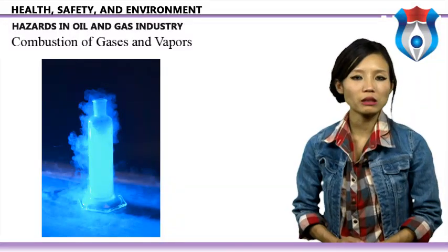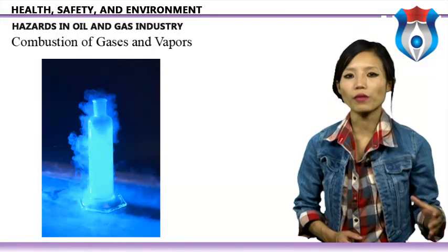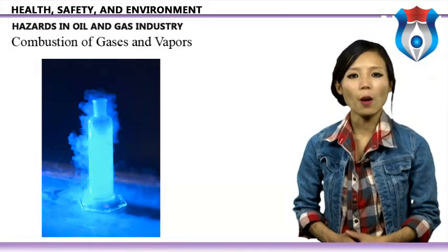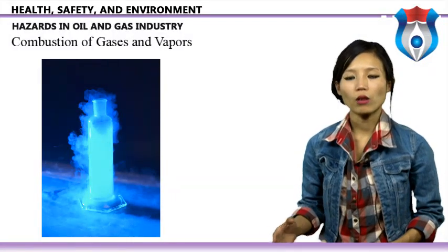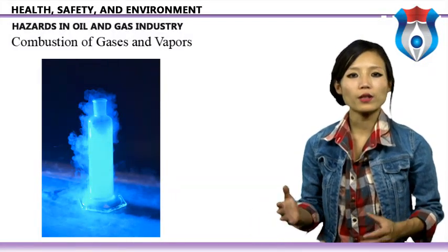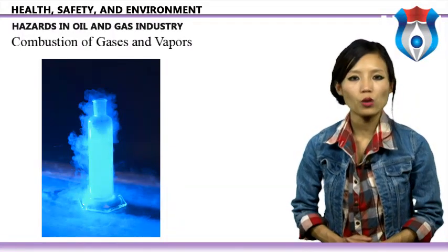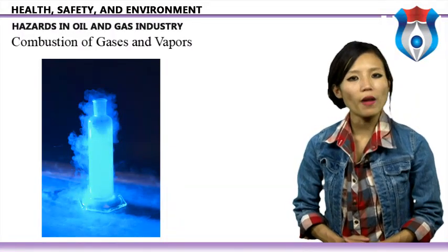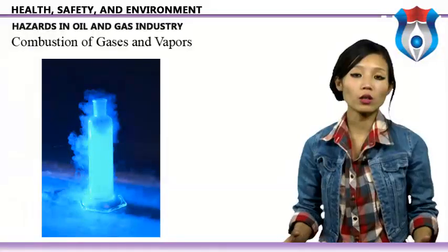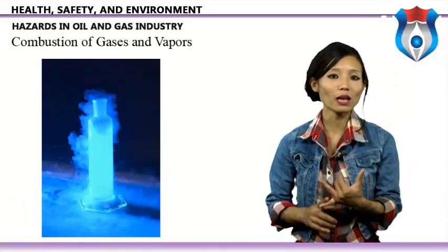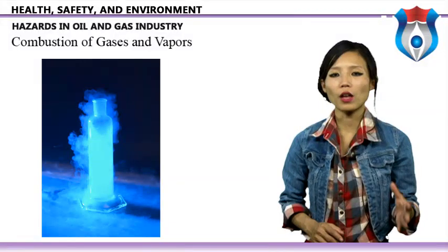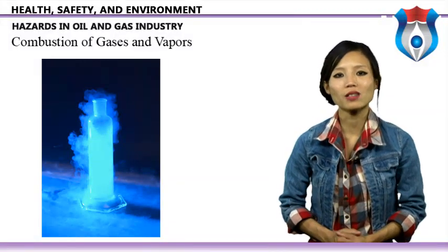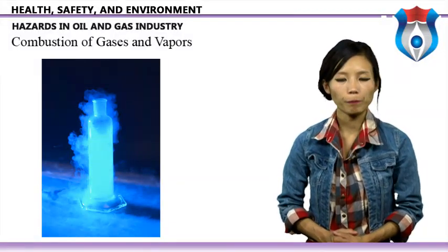In the petrochemical industry, the raw materials are a mixture of chemicals, many of which are decomposing naturally or are being altered by the processes. For example, crude oil is separated into many materials using processes referred to as fractionation or fractional distillation. Fractions are further converted using processes such as cracking or catalytic reforming. Flammable hazards are therefore likely to be presented by many substances on a typical oil refining plant.